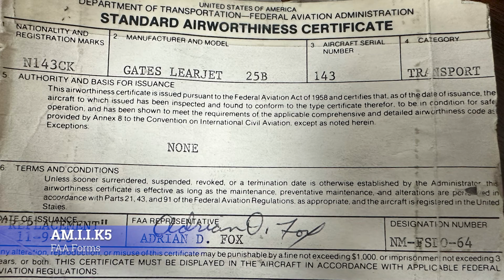All right, so the first one we're going to cover is going to be the A100-2. It looks like a little card like this, and it has to be on public display of any certificated aircraft. That's just a rule with the FAA on anything. If you have a certificate, just like the one here at this school, or at a 145 operation or a 121 operation, there has to be a place where the public can view that certificate. In this case, the A100-2 is the certificate for the airplane that says that it is airworthy, and it met all of the requirements of the FAA before it went into service.